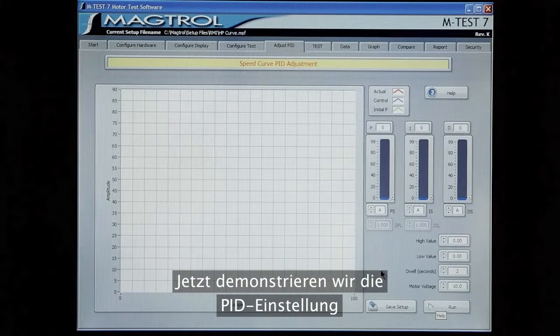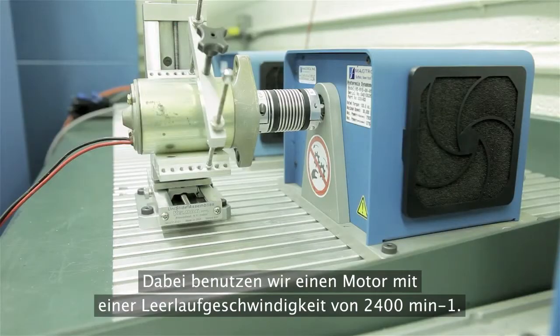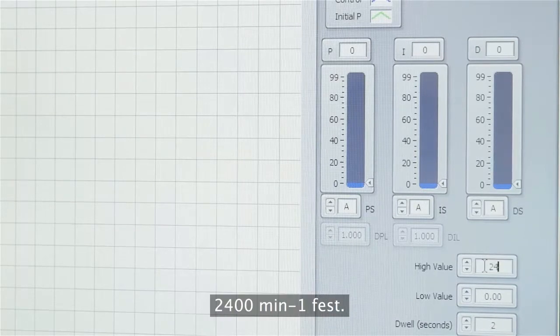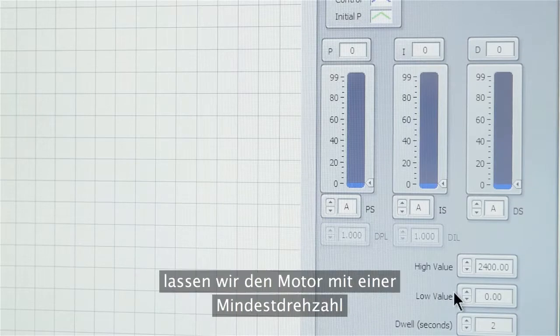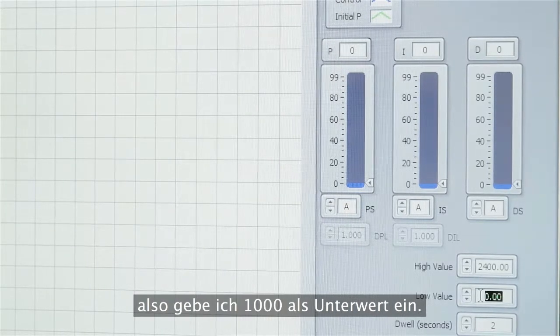Now we're going to show the PID adjustment for a speed stabilized or speed curve test. The motor we're using free runs at about 2400 RPM, so I'm going to set the high value to its free run speed of 2400. During the test, the lowest speed that we're going to run the motor to is 1000 RPM, so I want to type 1000 RPM into the low value.